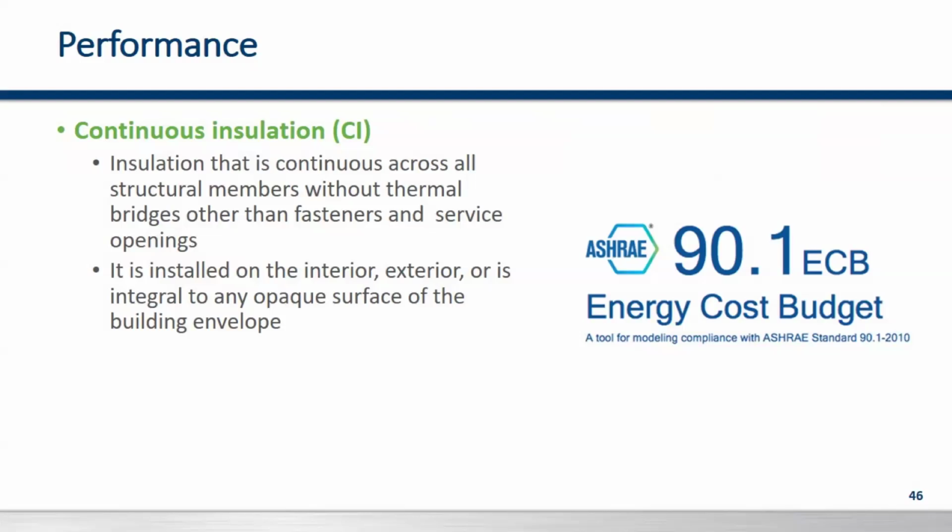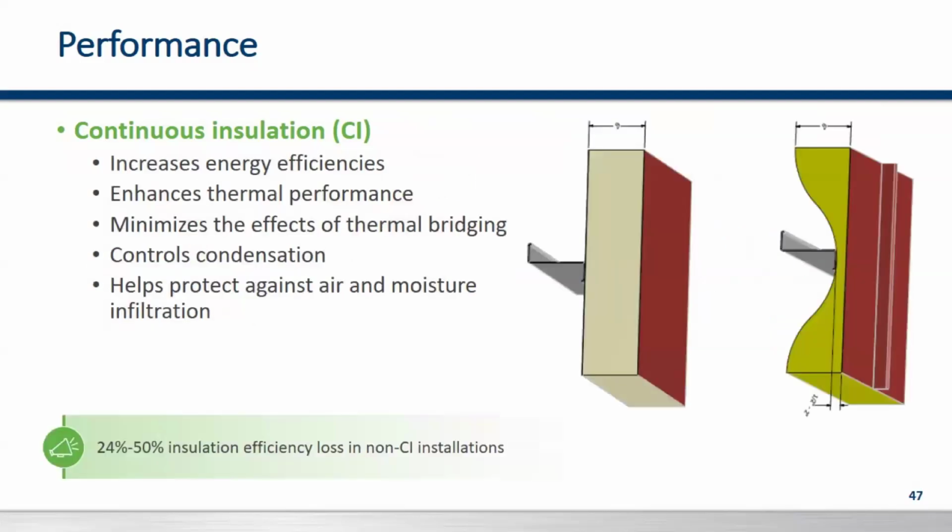And I'll show you an example of that. When we have traditional building systems, like a pre-engineered metal building with draped insulation, anywhere you compress insulation, you're going to lose R value. Let's say your overall design R value of the building is an R20. In the areas where it's compressed, you're going to lose R value, which could affect the overall performance of the building.